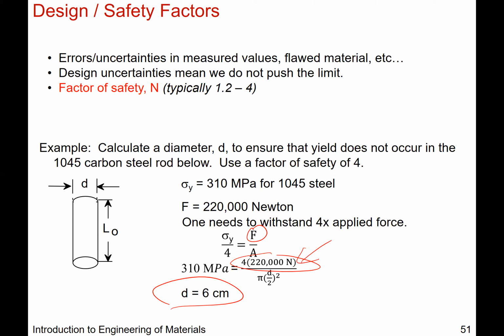So this range is affected by the end use. If it's a fishing line, maybe your design factor could be a little lower, like 1.2. So you lose a fish because your line snaps. Unless you're in the wilderness and really relying on that one fish for dinner, not the end of the world. Maybe you can forage some leaves, I don't know.